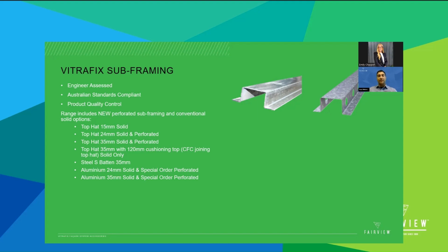behind the cladding panels. When selecting the profiles, it is also good to know what testing and engineering assessment have been provided by the supplier. For Fairview Weatherproofing profiles, load testing assessment and span tables are available to support design and to assist the facade engineers. Materials meet the Australian standard for G2 steel. Independent lab batch testing to AS1301 is available, and will be offered for the market.